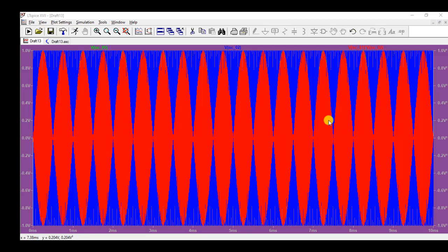We need to keep in mind that since we're doing it on a computer, we obviously aren't taking into account any dissipations that would be present in reality. What you'll observe on the CRO will be a bit different than this. Another interesting thing that we can do is to check if this wave really carries the various sidebands along with the baseband signal frequencies that we talked about. For that, we'll simply tell the computer to do the fast Fourier transform of this wave, or the FFT.